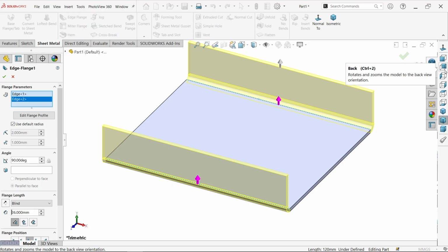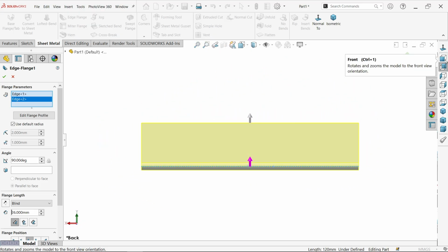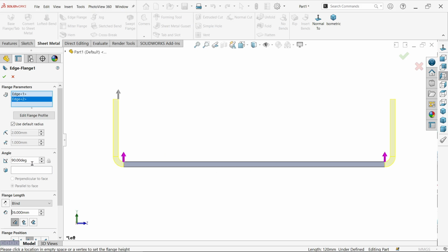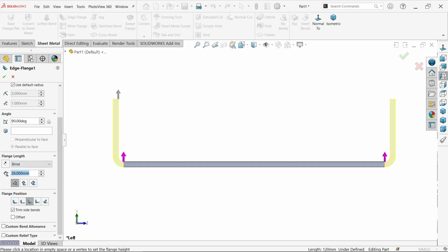Now let's check the side view, not this side view, this one. Okay, now angle, radius, everything by default, 90 degree, the angle between these two flanges is 90 degree. Now depth I want to make it 40. Okay, 40 from bottom to top. You will see here virtual sharp. Virtual sharp means the intersection point between these two outer edges somewhere here. Now material I am going to keep inside according to the drawing, outer distance